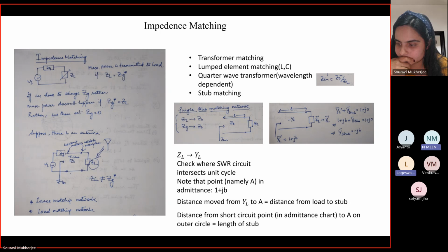No. If I am having a capacitive reactance or inductive reactance, then it must be a complex conjugate at that time for maximum transfer of power. But as far as transmission is concerned, Z0 must be the same, and then ZR will be the same as that of ZS. That is the maximum case. I am asking, suppose the load is 1 plus J0.2 and VSWR equal to 1, what should be the transmission line impedance? ZS will be the complex conjugate then.